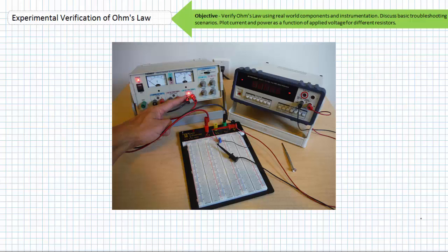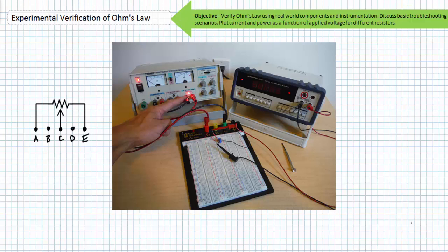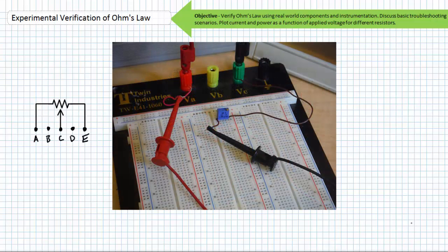Again, do not interpret an overload or an overrange as an indication of no current. An overload or an overrange is just the opposite. There's too much current because of the short. If the ammeter was in the maximum range and provided it was still readable, we'd observe the current limit of our power supply. Consider another cause for identical symptoms of too much current. What if the potentiometer was installed in our protoboard incorrectly?